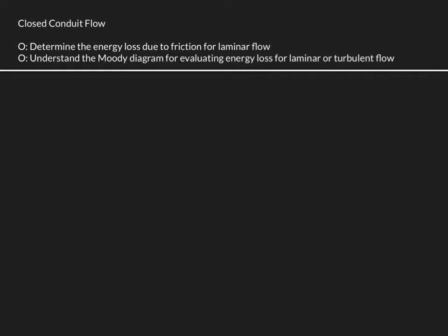And what's going to happen in these systems is we're going to start dealing with the friction and the losses that occur. And so, as I said early in the semester, one of the things that really excites me about this class is that we are going to deal with actually getting at friction and how to deal with it, okay? So in this class, with friction, we always refer to it as head loss. And head loss is this guy, HL, okay? And we're going to split it out into H sub F and H sub lowercase l. And this is just following the nomenclature of your textbook, okay?